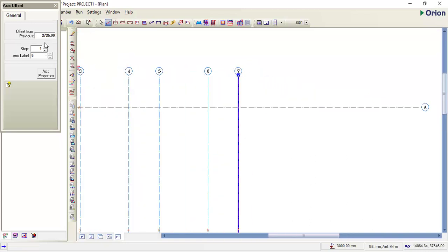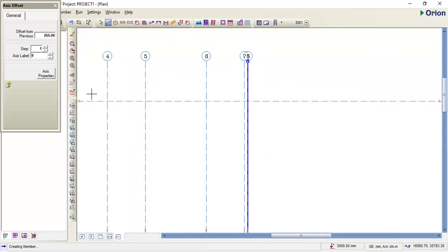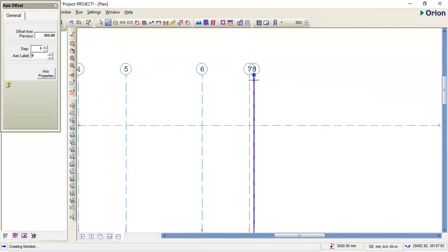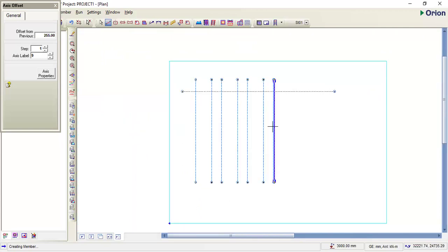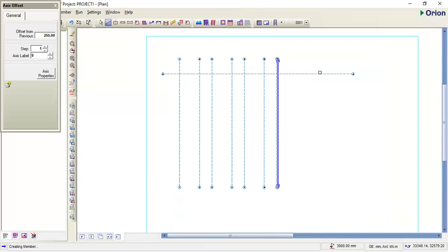Normally at the expansion joint, we have 25 in between the two grids. That is the expansion joint. So you have 25 mm, 1 inch, in between the beam or the block for the expansion joint. So this is what you have quickly.